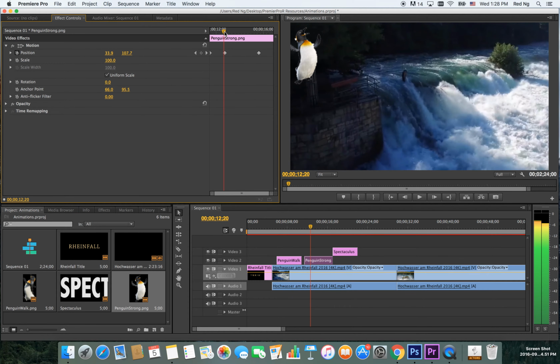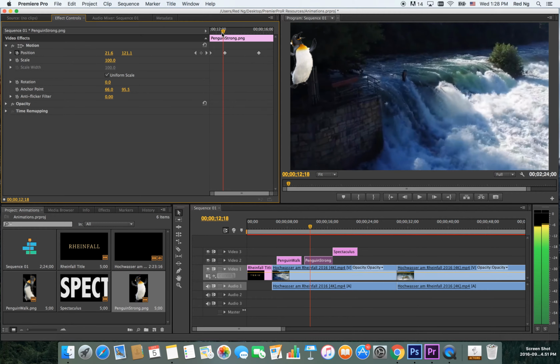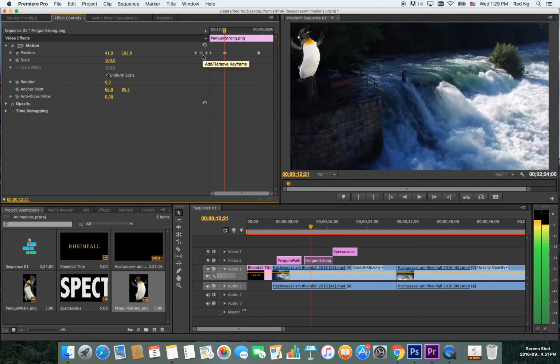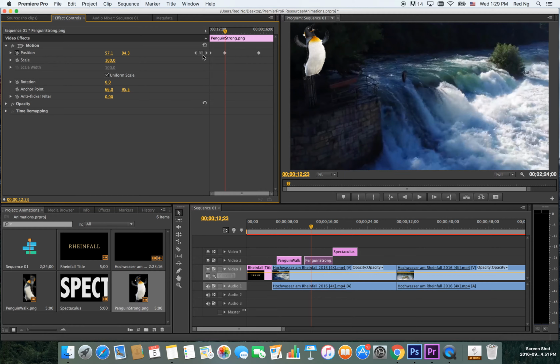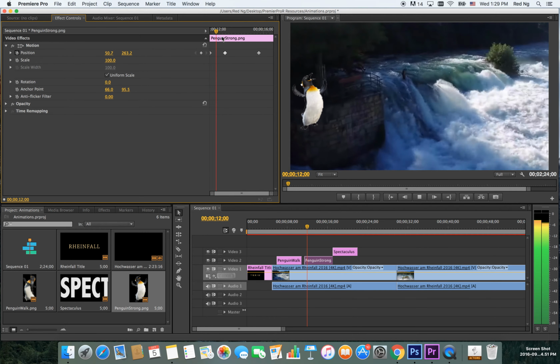what you want to do is go back to the particular keyframe. So how do I come back to this keyframe to edit it? Right now you can see I'm right around the keyframe and I have a circle here that is not solid. I can use the left and right arrow keys to move the timeline until the point where, hey, I'm on this keyframe now. So what I can do is move one frame down, and then right now I'm outside this keyframe, okay? And I add another keyframe here. So the two keyframes. So play.